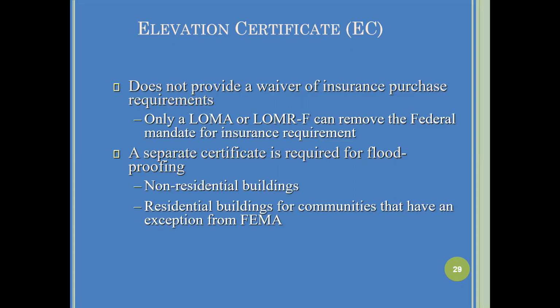Only a LOMA or LOMR based on fill can remove the federal mandate for insurance requirements. A separate certificate is required for flood proofing, and that's only applicable for non-residential buildings. And residential buildings for communities that have an exemption, and those exemptions I think are very rare.